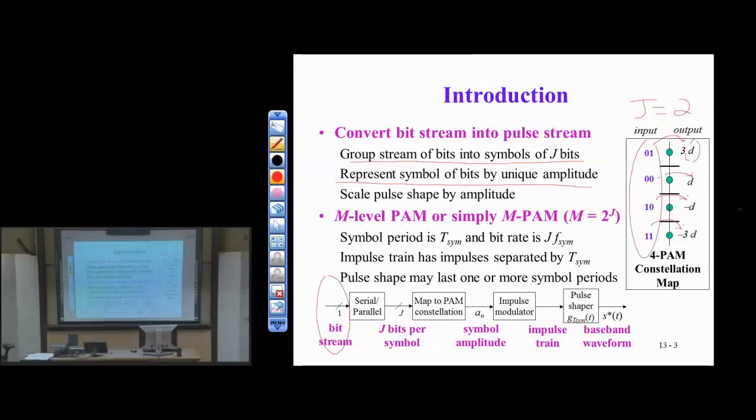So there's a trade-off. If we increase D, the good news is that it improves our signal power. That means we have more signal power that will get to the receiver, and hence a higher ratio of signal to noise power. The bad news is that a higher D puts a lot of stress on the analog circuit design in the transmitter, and stress on the receiver side.